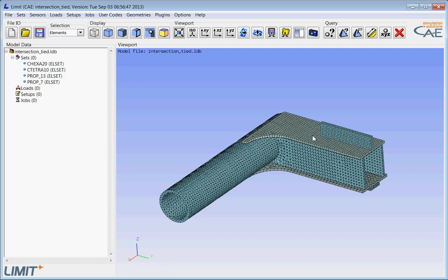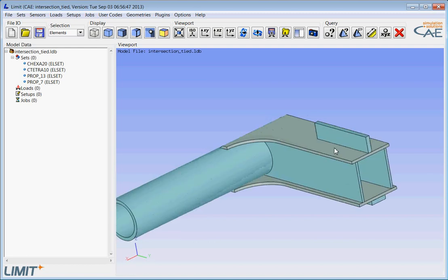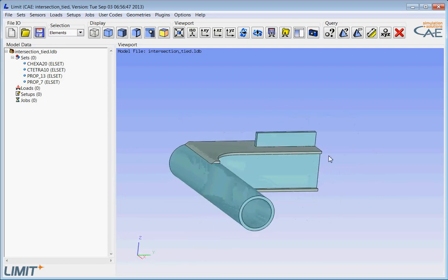We can do that in an averaged sense, which means that we can use these stress values for codes that are based on nominal stresses, and we can also use the structural hotspot concept like it is described by the IIW. In our case, I will use the DVS 1612, which is a code for welding in the rail business.